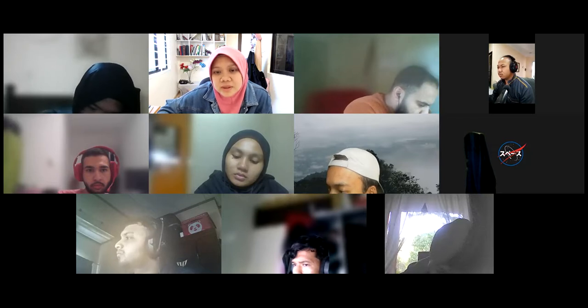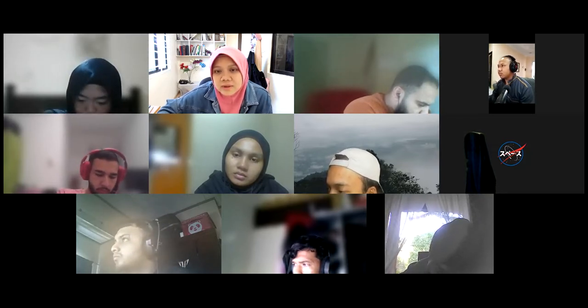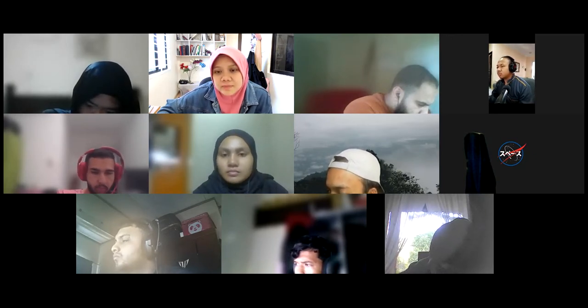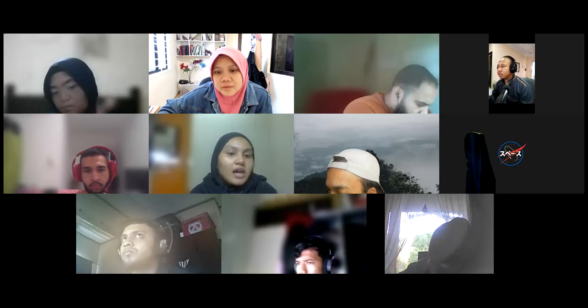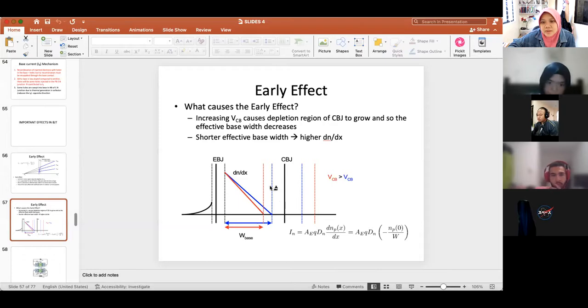Therefore, what happens to the recombination? When the effective base width becomes shorter, what happens to the recombination, Aiman? It will become less recombination. Good. So when you have less recombination, then what happens?